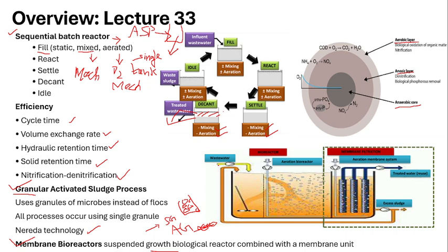Here the wastewater is coming in. It is agitated using a mechanical instrument and then aerated. With aeration, the microbial organisms grow in numbers and take up the organic material. Now in this region, this is the membrane filtration, the aeration membrane system, where the biological organisms are taking up the waste material and the treated water is also clarified in the membrane system itself. The treated water is taken out for reuse, and the sludge is collected and removed here at the bottom. So this is the working of the membrane bioreactor system.